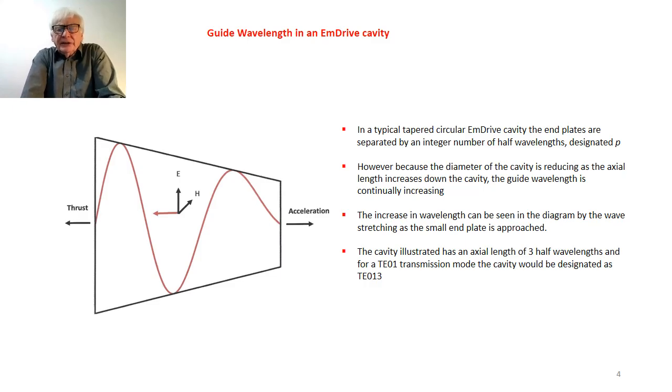The cavity that is illustrated here has 3 half wavelengths, and therefore for a TE01 transmission mode, the cavity itself would be designated as a TE013 cavity.